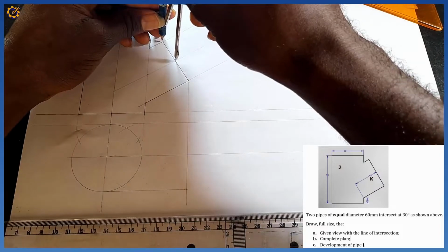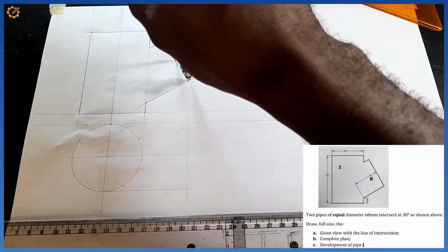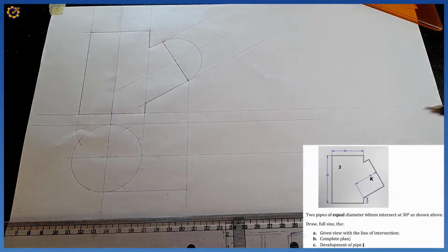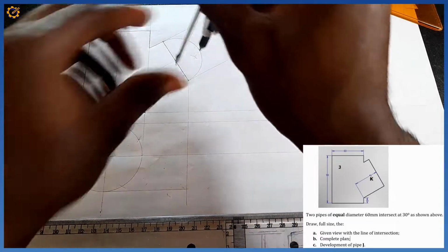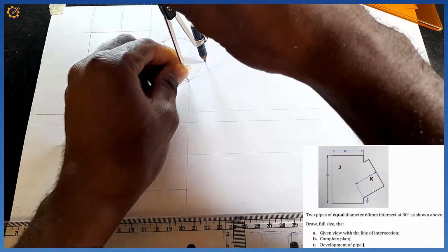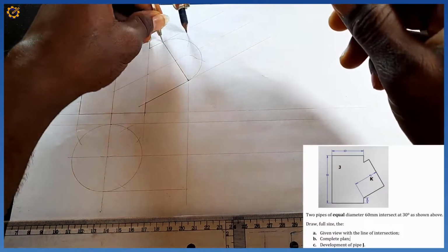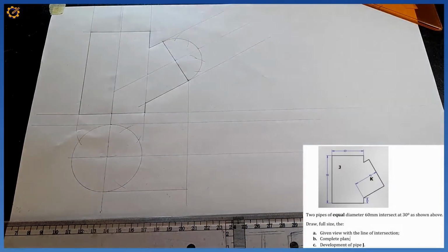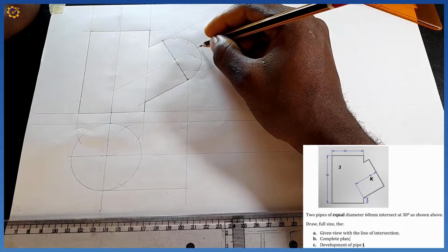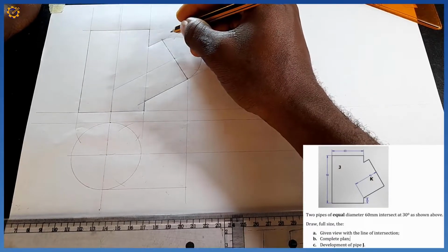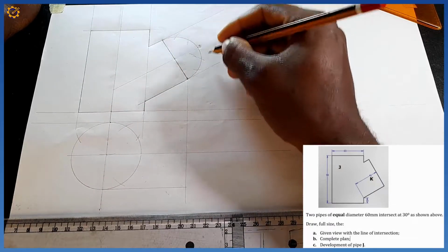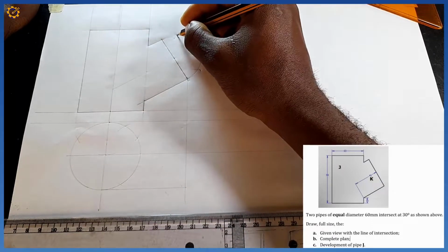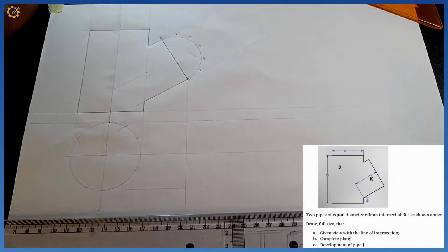Okay, yeah, this is the radius right there. I'm going to produce that, then I'm going to divide that into 6 equal halves, like that, standing right here, bottom and top. So with my pencil, I number this mark 3, 2, 1, 0. This 2, 1 and 0. Okay, do you see that?